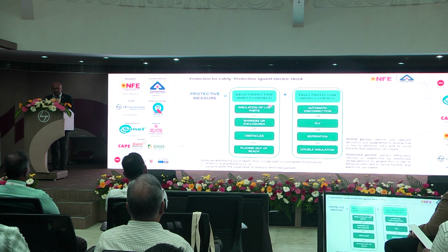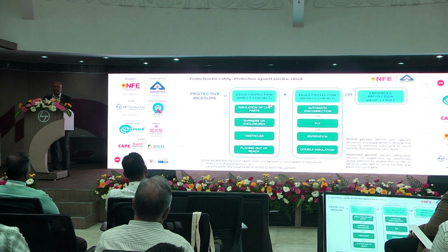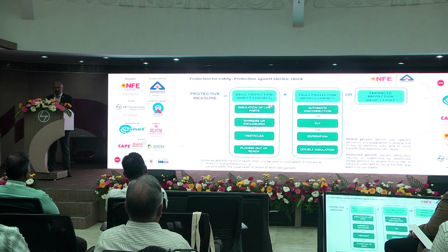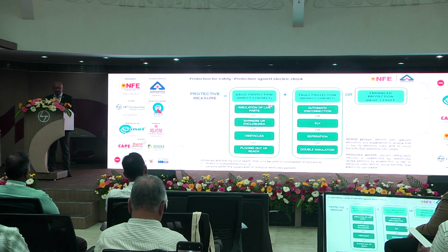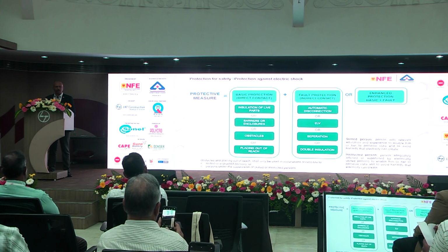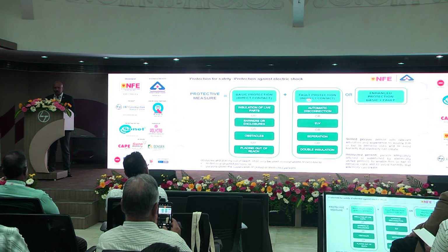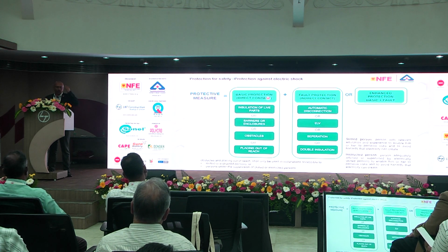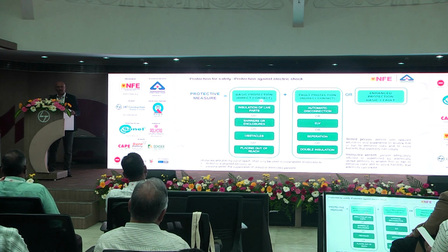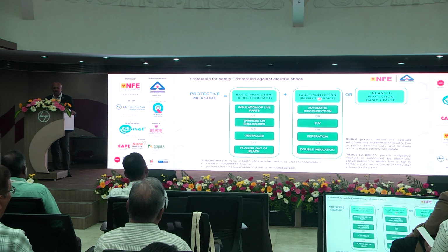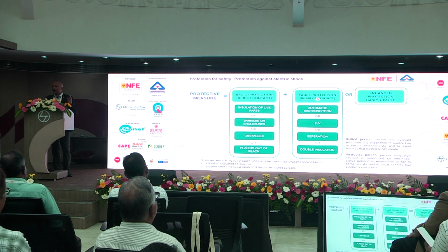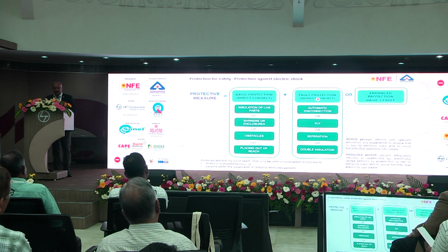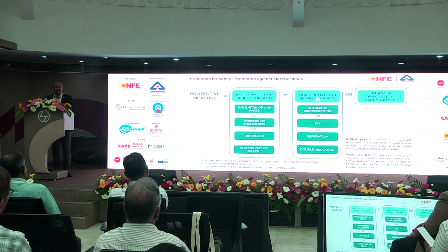Now, to achieve that, we have safety measures called basic and fault protective measures. Basic protection, earlier we used to call protection against direct contact, and now we call it basic protection. In the new, upcoming standards, you will see basic protection, and for indirect contact the new name which is followed internationally is fault protection. Earlier we called protection against direct contact and indirect contact, now we call them basic protection and fault protection.